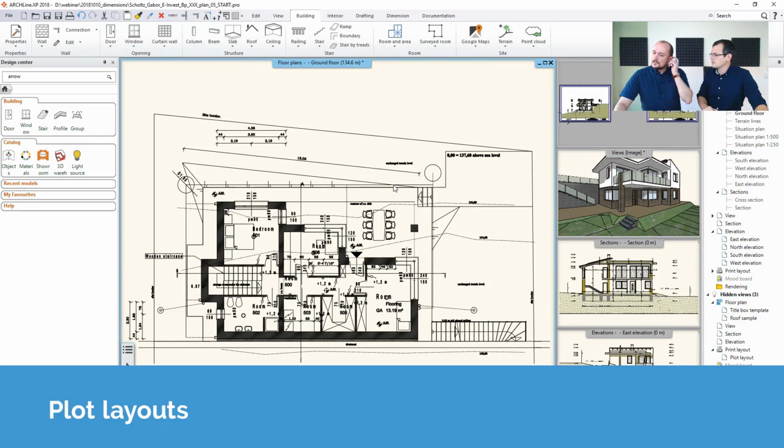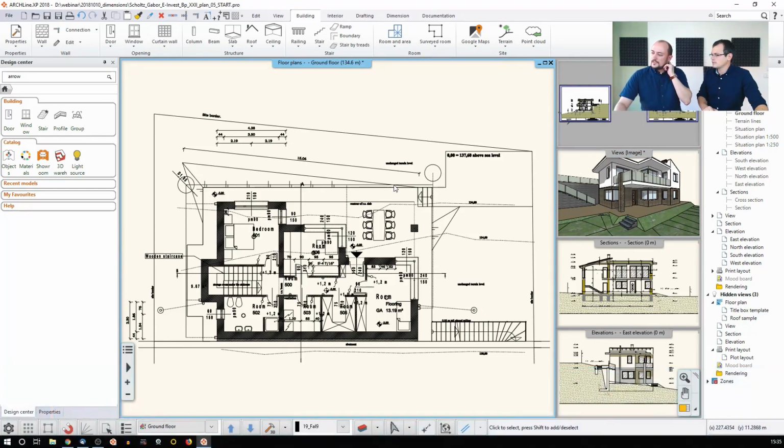Okay, so what we already have here, I already actually created 2 layouts, but I will just add this one up to the other ones. So actually, the difference between a layout and the drawing itself, that this is a preparation to print or publish. This is the original drawing. This is where you make the detailing and everything else, and then you decide on what size of paper with what sort of text and everything else you would like to use it.